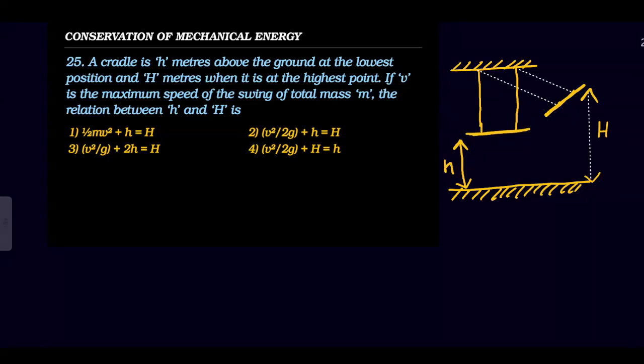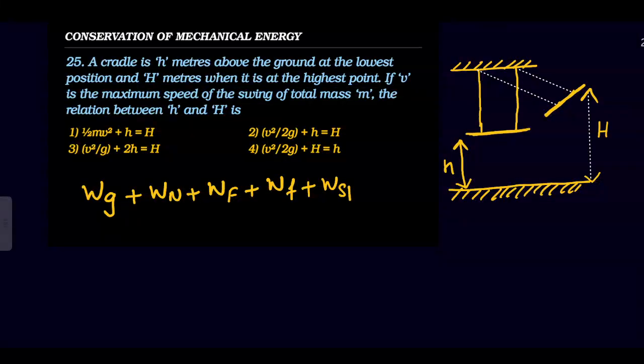Yes. Now you tell me, here we need to find the total work done. Work-energy theorem we have to apply, by using work done analysis. So this is work done: work done by the gravitational force plus work done by the normal reaction plus work done by the applied force plus work done by the frictional force plus work done by the spring force equal to delta KE.